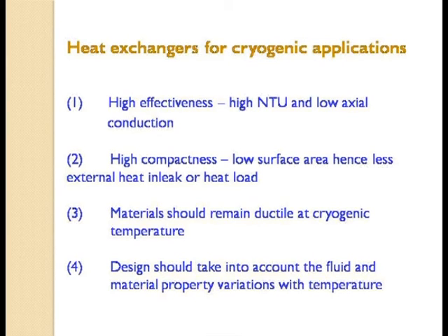Okay. So then less external heat leak, that we have talked about. Then materials should remain ductile at cryogenic temperature. While making heat exchangers there are many materials, but while choosing materials for cryogenic applications, you should be very careful that they don't become brittle at low temperature.